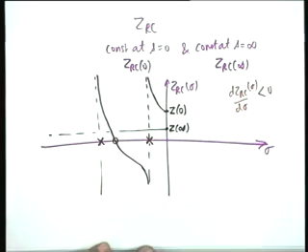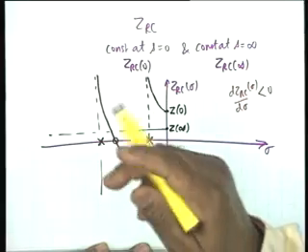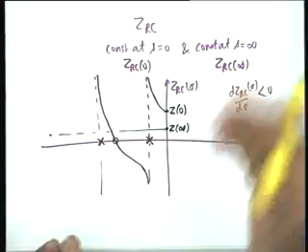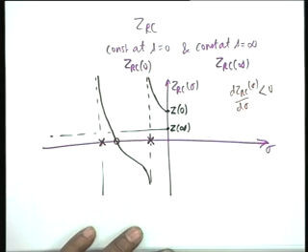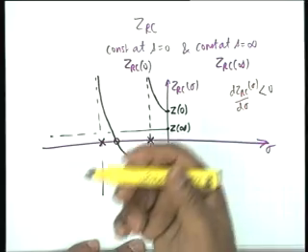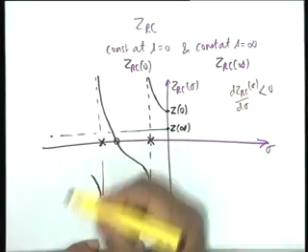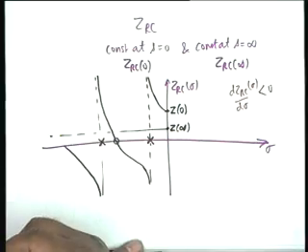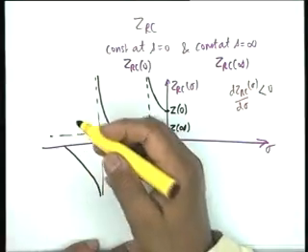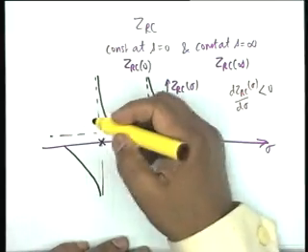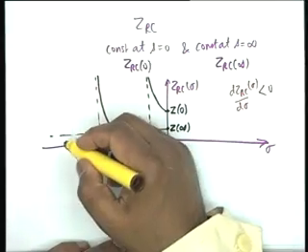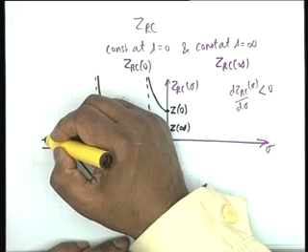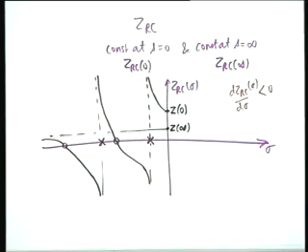Yes, it can take negative values. If sigma is negative, obviously it can take negative values. You see, positive real function simply says if s is real, Z of s is real. Okay, what can happen next? It can repeat. It will rise from here, then it can go through a 0, it can go to another pole. But suppose that is the end. Suppose there are no further poles, then obviously there will be a 0 here, and the function will asymptotically go towards Z of infinity.